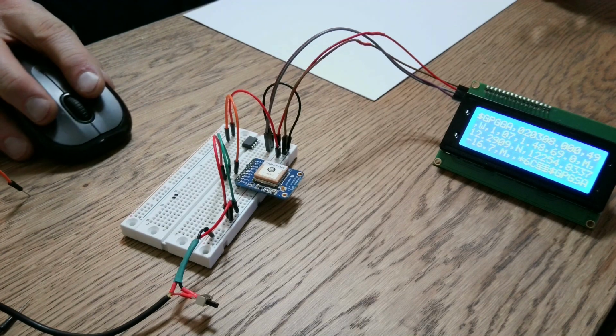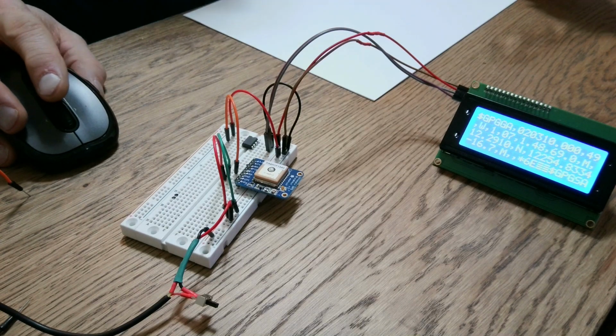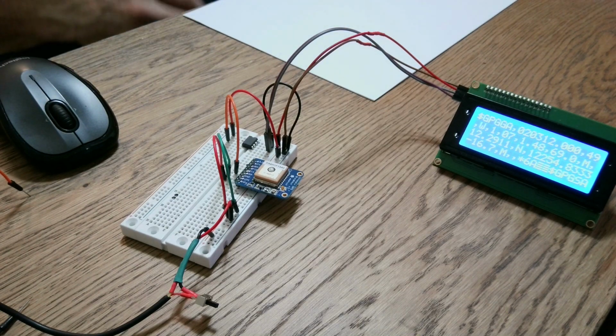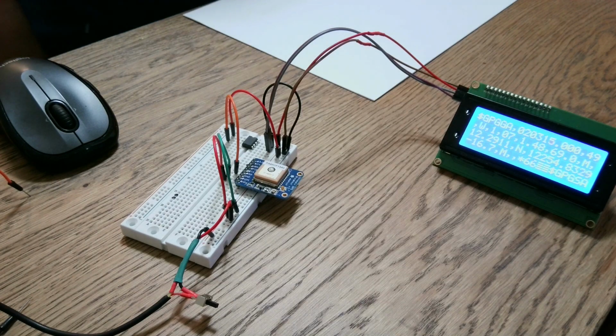So this is the project right here, as you can see, and the GPS module is a lot simpler than you might think. It's not that complicated. Matter of fact, we're going to look at the waveform coming out of the transmit line, the TX line, and we're going to put it on paper, and we'll find the first 2 bytes of characters, which, by the way, you see up there in the display, is a $ sign and a G.